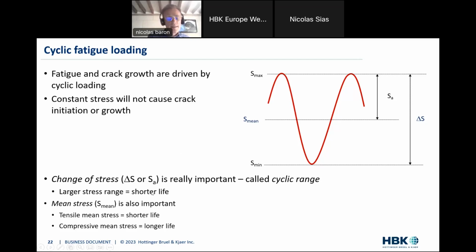And specifically, depending on whether this average of stress is positive or negative, so whether we are dealing with tensile mean stress or compressive mean stress, that will be either beneficial or detrimental to a design. As highlighted here, when the stress is tensile, you tend to enlarge the small cracks. So in the end, it will be detrimental, because the small cracks that just started will extend, they will grow in size, and in the end this will lead to a fatigue crack.